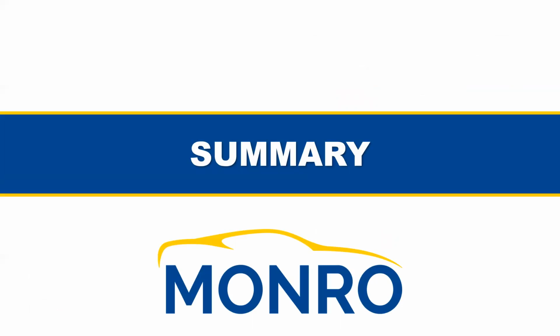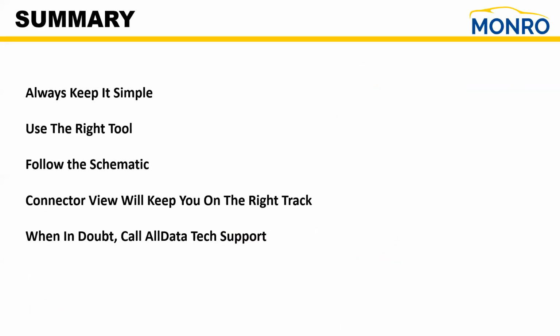So remember, always keep it simple. Always think your way through it. Look at how the circuit acts, and that will help you determine where the fault in the circuit is. Use the right tool for the right job. Always follow the schematic, and remember, the connector view is going to keep you on the right track.